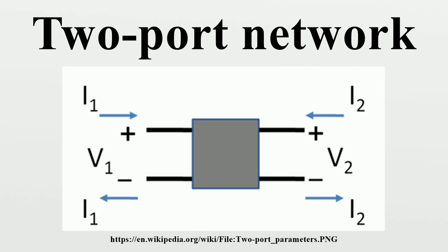Collapsing a two-port to a one-port. A two-port network has four variables, with two of them being independent. If one of the ports is terminated by a load with no independent sources, then the load enforces a relationship between the voltage and current of that port. A degree of freedom is lost. The circuit now has only one independent parameter. The two-port becomes a one-port impedance to the remaining independent variable.